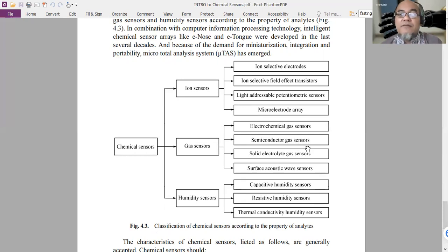The dielectric material, for example, if we make it porous, it can absorb water vapor from the surrounding atmosphere. Then it will be sensitive towards humidity. The epsilon R, the relative permittivity of the dielectric material between the two electrodes, will change depending on the water vapor content of the surrounding atmosphere. Then we can function that capacitor as a capacitive humidity sensor.